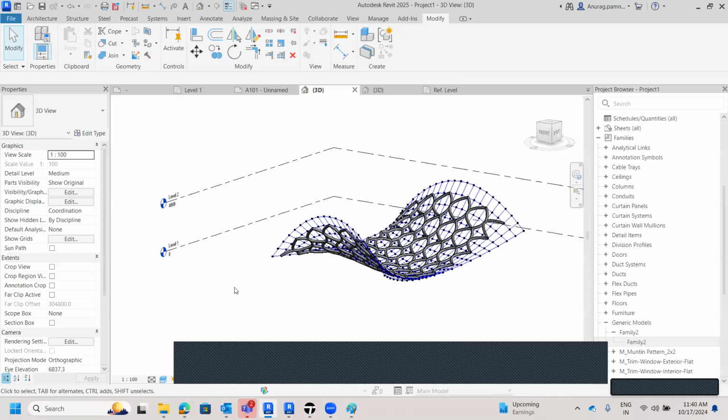So you don't need to place mass on the building aspects of it. Once you have your building and you are designing for the facades, you will be developing a mass around your facade accordingly, and then you will be placing these components onto the facade. So you have a structure already, and then you're going to work on its envelope. That's the case: you have a building, you set the reference plane, and you mass it according to the shape, and then you impose these elements onto your mass part under the facades.